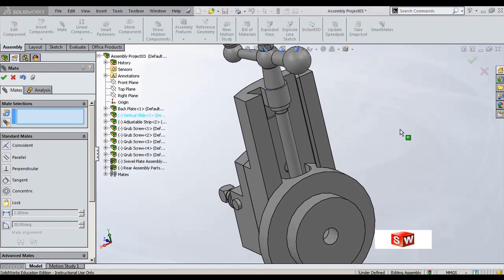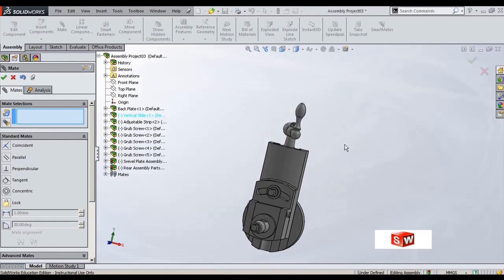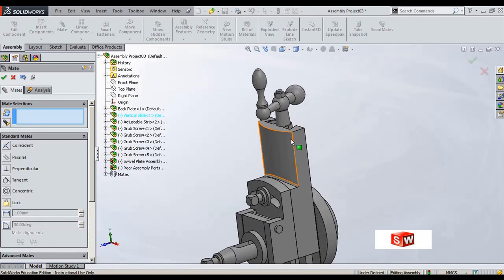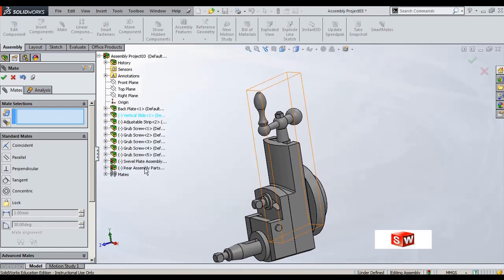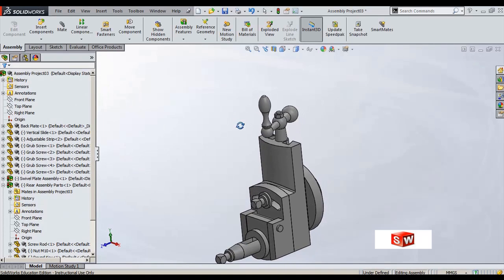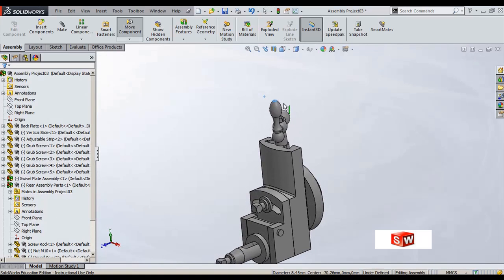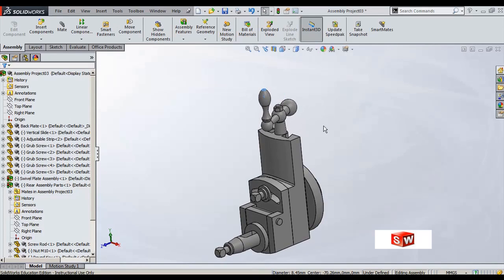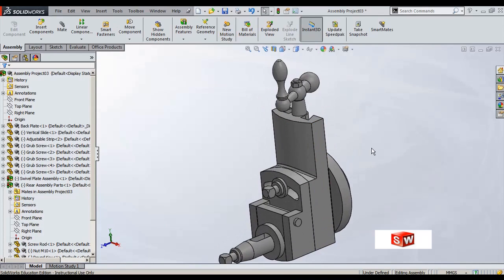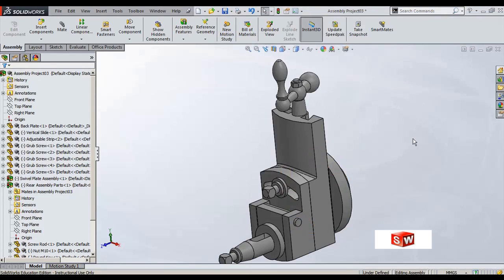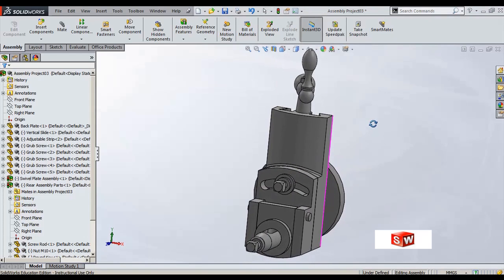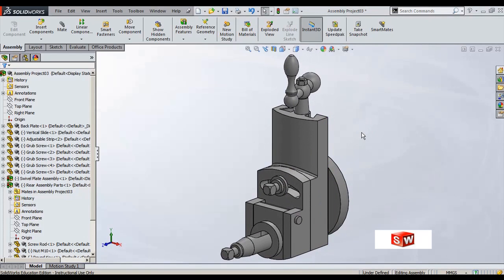So it should coincide. Now you can leave it as it is, or if you want to move this component, or keep it specifically in any direction or rotation, you can place the handlebar, everything as per requirement. Okay, so this is how we can do the assembly of parts, which has 19 components, by doing sub-assemblies, and we can complete the assembly as well. And we found that there is no interference in the entire assembly.